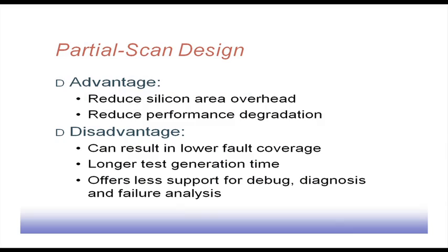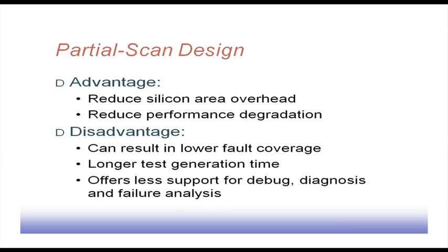Disadvantage: it can result in lower fault coverage, because we are not having control over all the flip flops. So, naturally there may be a fault coverage problem. Test generation time may be longer, because in many cases we have to use sequential ATPG, and sequential ATPG algorithms take longer time to run.